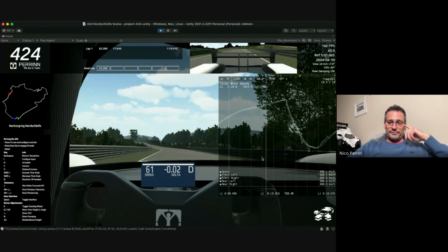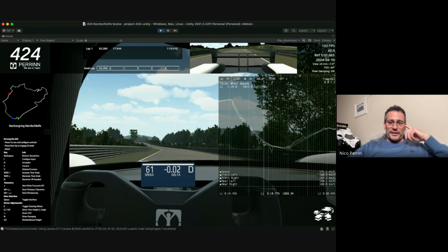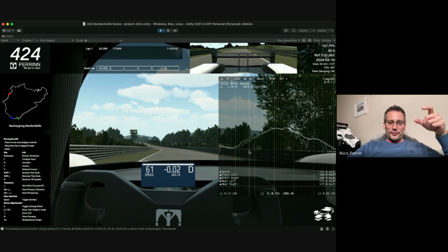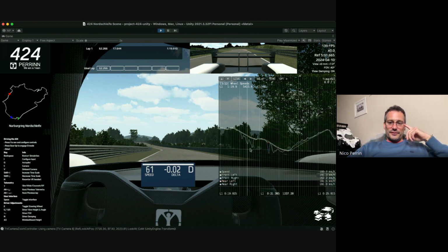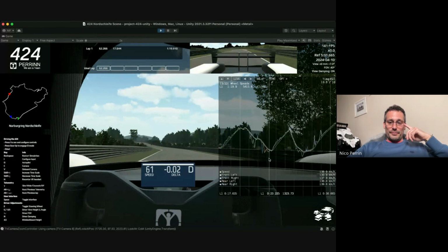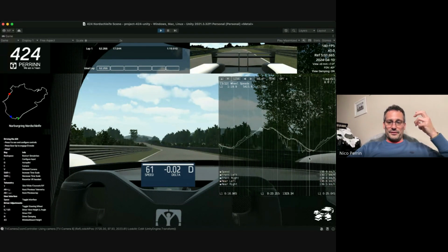Okay, let's keep going. Let's go to turn 3. The braking is fairly good here. There's no big amount of lock, just a little bit of front locking, but it's not much. Here you get a little bit higher front slip than rear on exits. So it might tell you that if anything, our power balance is slightly too much to the front at that point. So you can see so many different aspects of the car balance.